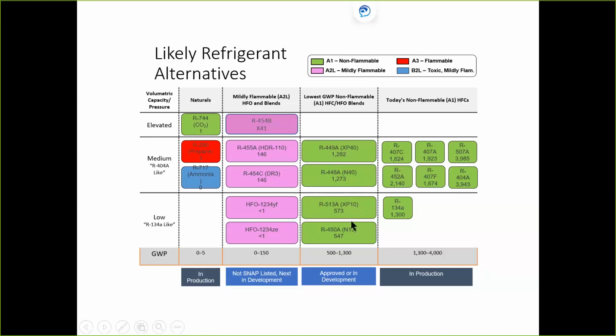Here's another one that's coming out quite soon, already out. We don't hear a lot about it just yet, but the testing's been done. This is a great replacement for 134A. It's called 513A. In fact, recently I suggested we change our refrigerant over in our small simulators just in case we were to travel over the state line in California, where a lot of these things, the SNAP 20 and 21 and the CARB things are already going into effect. They're ahead of the U.S. as a whole. So we decided, the engineers did some testing, and they came up with the least path of resistance for changing the least amount of components on our small trainers would be R513A, okay? So very, very similar to that.